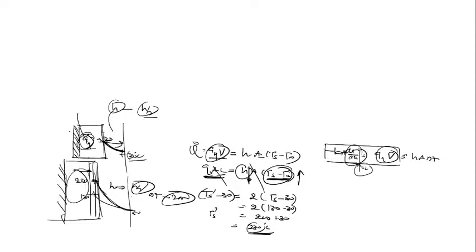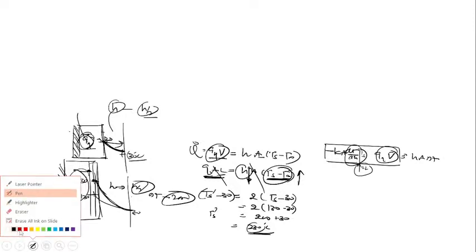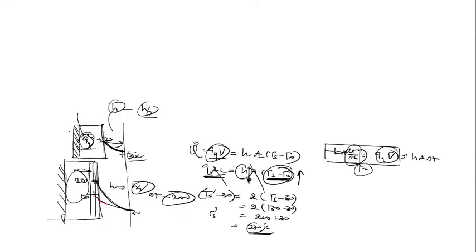Then whatever the slope is, try to understand, a very important thing, although I will clear it in the next lecture also. If this is the profile and this is the new profile I got here, what is the same here? The gradient will remain the same. The temperature gradient at x equal to L will remain the same. Why is it the same? Because whatever heat is transferred by conduction is equal to that by convection, and convection is nothing but Qg into volume, the rate at which heat is transferred at the surface. This is Qg into volume. Qg into volume is the same, so dT upon dx will be the same, and the slope or gradient will be the same here.